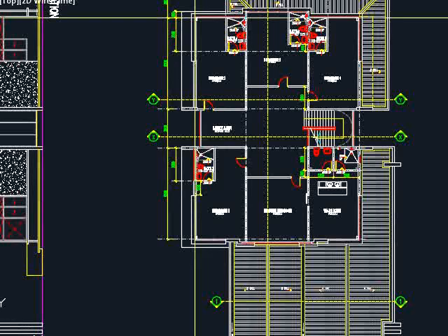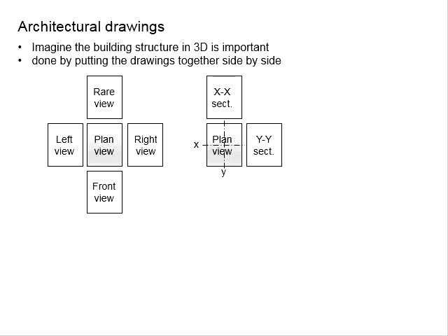The principles apply. With that said, you have an idea how you're going to read the architecture drawing, and you know the importance of reading the drawings in 3D, so that you have a better imagination of how the building should look, and you have less possibility of errors or mistakes, especially on those detail parts that can compromise the aesthetic view of the buildings. It is our obligation to meet the requirements of the architects. They have their own design, and there are always solutions for us to overcome the design. We need to be creative in terms of the solutions, instead of always asking them to change the design.